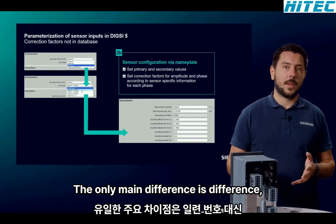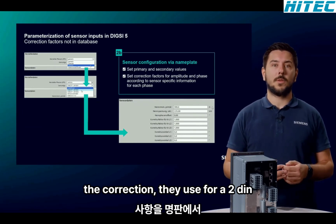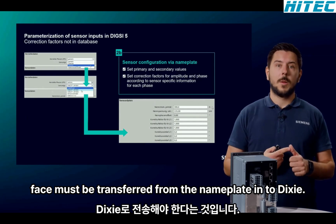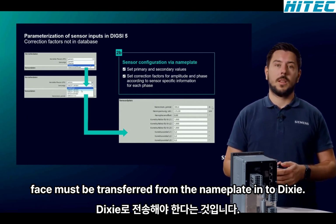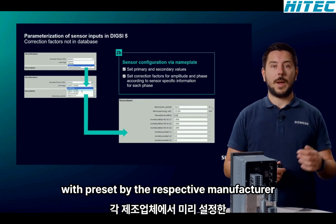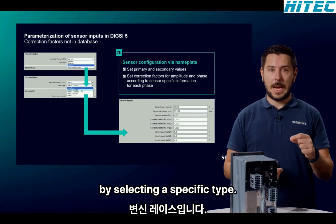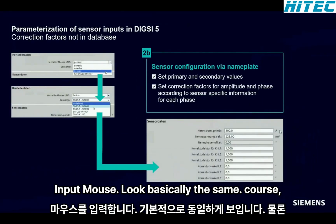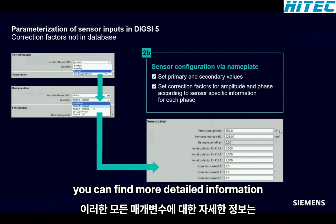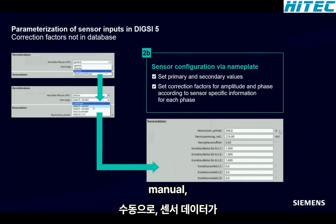The only main difference is that instead of the serial number, the correction values for amplitude and phase must be transferred from the nameplate into DIGSI. The transformation ratio is preset by the respective manufacturer by selecting the specific type, but can also be changed. The input mask looks basically the same. Of course, you can find more detailed information on all these parameters and the settings in our device manual.